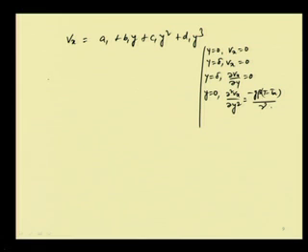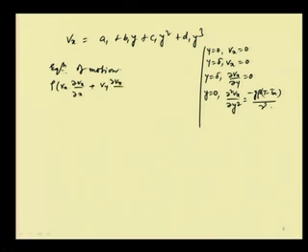So, the equation of motion says, as already discussed, according to the equation of motion, rho into Vx into del Vx by del x plus Vy into del Vx by del y, which we have just seen from the Navier-Stokes equation, is equal to rho g beta into (T minus T infinity) plus mu into del square Vx by del y square.